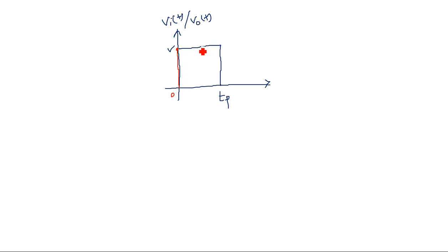Now as the input voltage is a constant voltage, the capacitor slowly charges, so the output slowly discharges. Meanwhile, there is again a sudden decrement of V volts in the input, so the same should appear in the output, V volts down. Remember, this height is equal to the input, the height that is decreased here to here. The output goes down by the same amount, but it should stabilize to 0. That's why again it is going back towards 0. This is the time axis. Okay, this particular peak is known as undershoot.